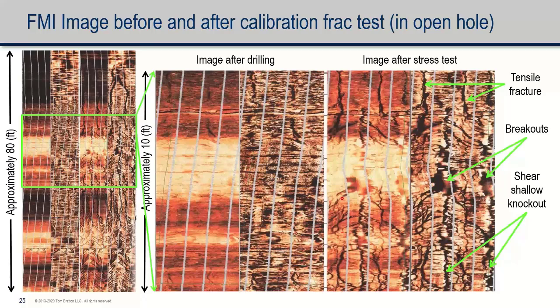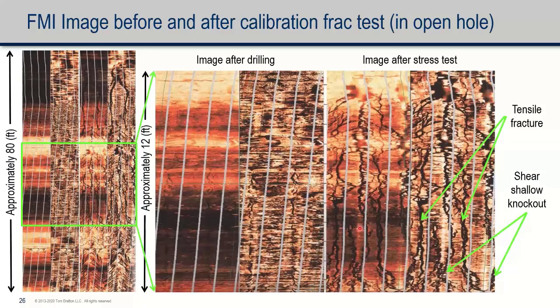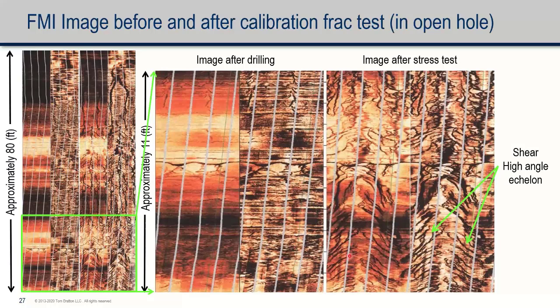We get down here and we get a lot of damage in the direction of the maximum horizontal stress, and we see damage in the minimum horizontal stress direction. So I think I can explain what we're seeing there. As we go down deeper, I'm seeing the same kind of behavior. I see some splitting that we have here, but overall, these apertures are quite a bit less than if it's induced in tension. And then finally, we get down to the bottom, and this formation down here is failing totally in shear. It's not failing in tension at all.